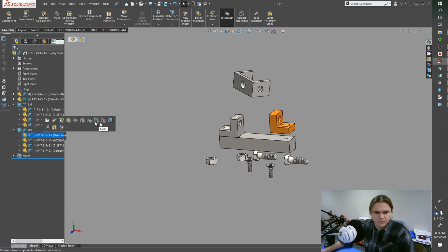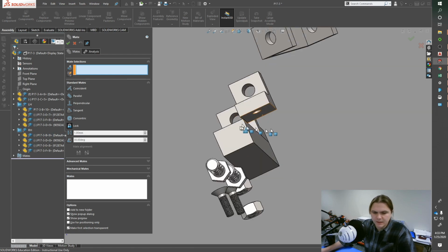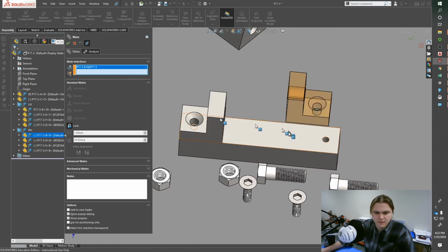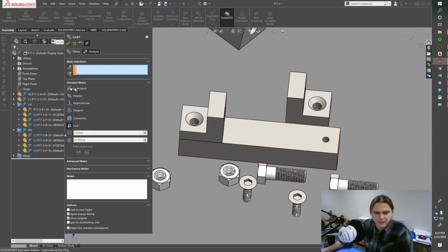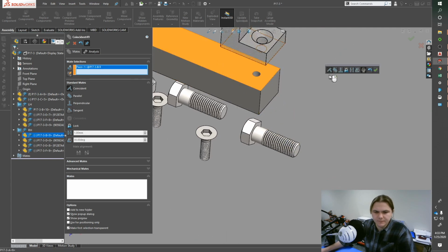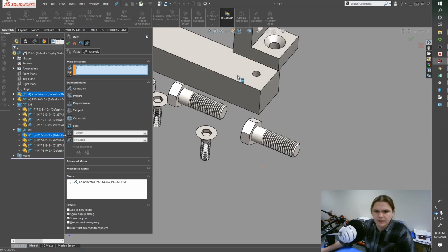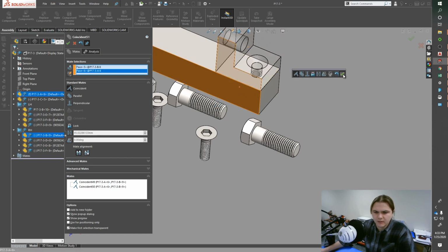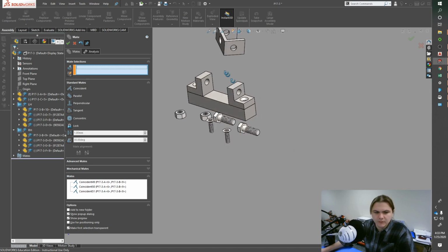Let's do this one again real quick. I'm going to do this a little sloppy. Like I said, I prefer doing front, top, right, but in this instance, I'm just going to do surfaces to surface. Oh, see, I just made the mistake. You've got to make sure to get this all cleared out so then you can select it to coincident. There to there, check. There to there, check. And here to here, check. Not sure why my computer's freaking out with all these errors, but whatever.